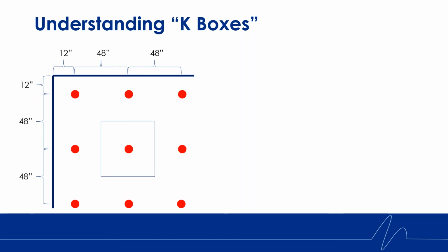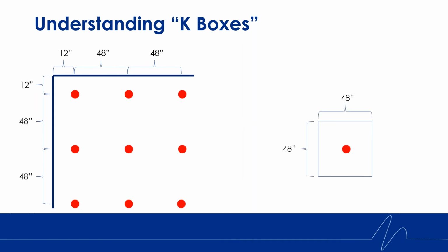and do that for the other three partners, we have developed the tributary area, which represents the equal spacing between itself and its neighbors. In this instance, we have a 48-inch by 48-inch tributary area, 24 inches to the top, 24 inches to the bottom, and left and right, which contributes to a 16 square foot trib area for this isolator. If we were to do the same for the two up top, we do not have isolators neighboring north and west. So for these instances, we will go to the perimeter of the isolated ceiling.